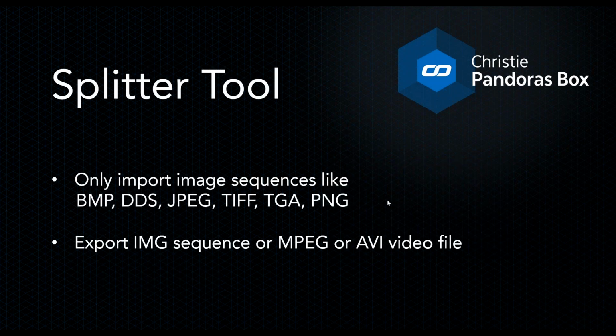Some more information: you can only import image sequences or still images like bitmap, DDS, JPEG, TIFF, TGA, or PNG. It's not possible to load video files, only image sequences. On the other hand, you can export video files like MPEG or AVI, and image sequences as well.